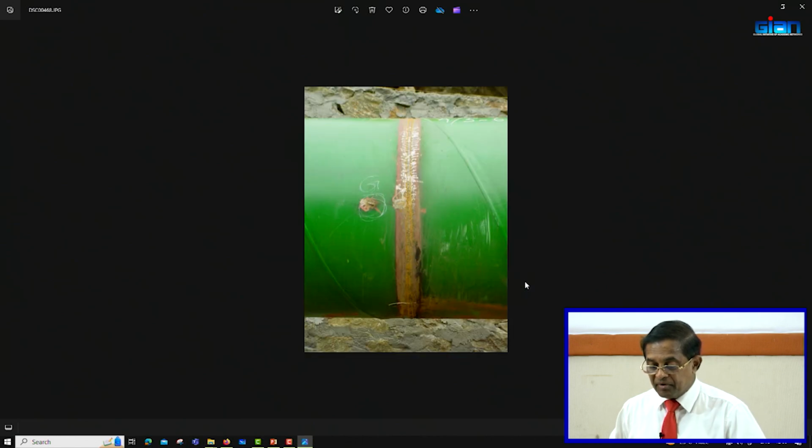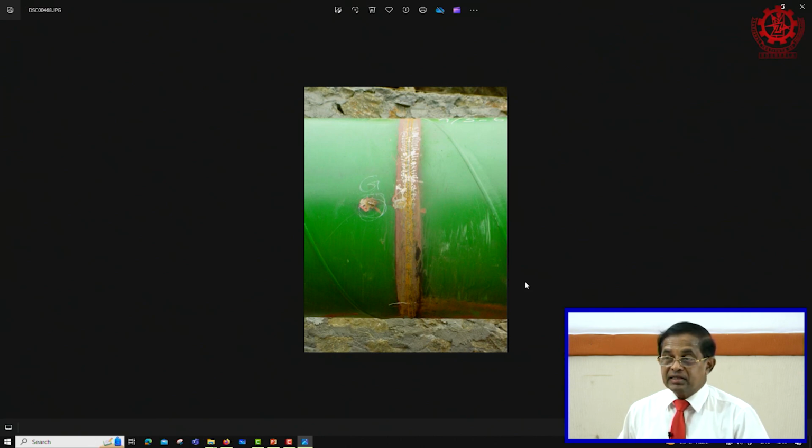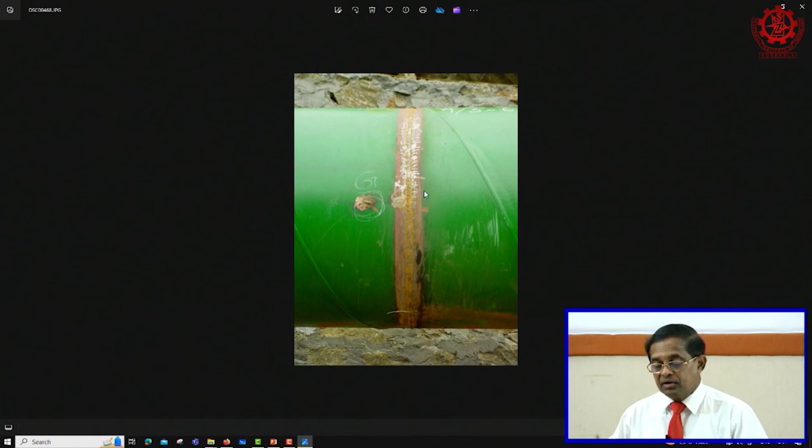Here is welding being done. It should be an X-ray quality weld. So, welders have to be tested and qualified for X-ray level grade testing. Normally dockyards and testing agencies can test them. They will ask them to do samples and then see whether there are inside air pockets and other defects. If they cannot do a continuous thorough welding, they are not qualified as X-ray quality welders. Even after this, on a select 10%, 15% of joints, we will keep an X-ray source inside and take X-rays to see whether the joint is okay, because it is critical, as it is subject to heavy pressures and can be damaged.